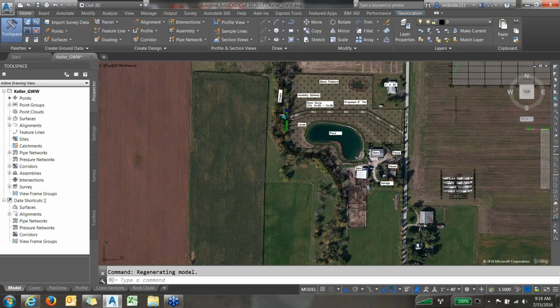So whatever you lock it as, that's what you're going to get. So you want to get as close in as you can when you clip that and lock in your view, so that if you do it from out, you're going to have a very coarse resolution, and it might not look good if you start to print little detailed drawings with the aerial in the background, like he just showed.